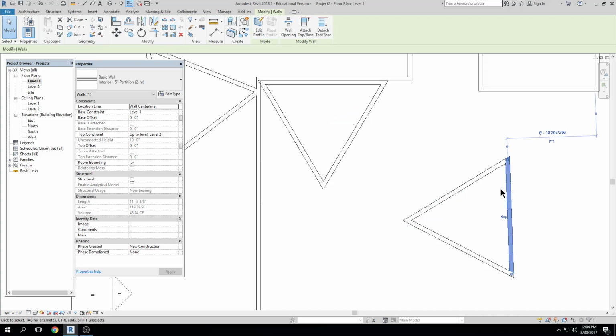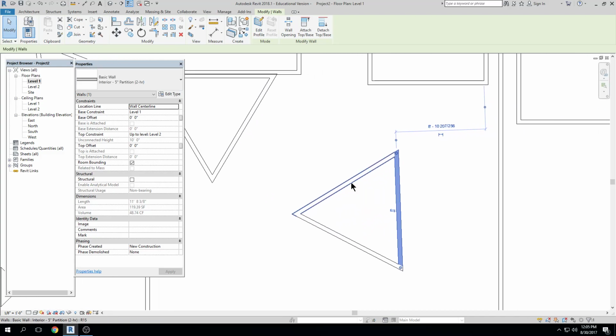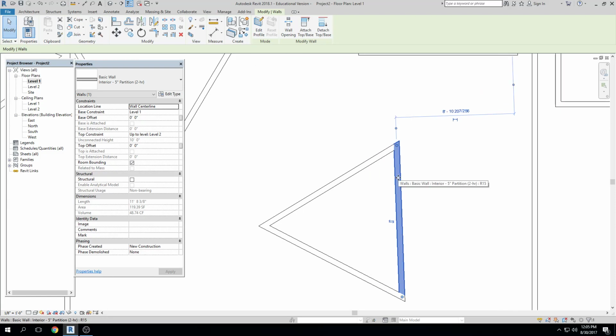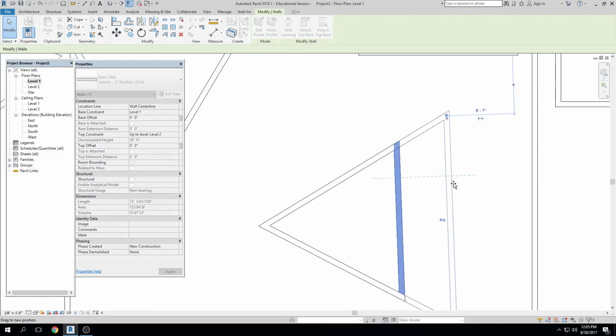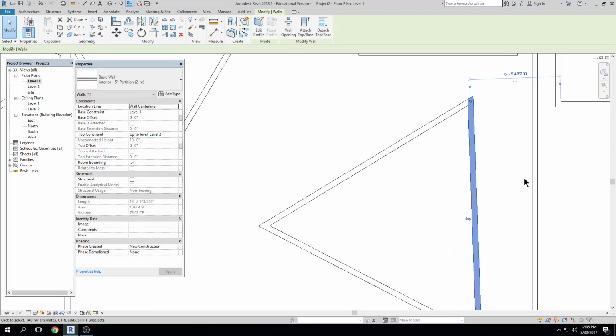Okay. I can also drag an object. I don't suggest it because I think that sometimes when you drag, you may also select something else that you're unaware of, which happens all the time. Probably where most mistakes happen is when you're new at Revit and you think, oh, I'm going to make this bigger, I'm going to drag it, which if you hover over a selected item and that little crosshair pops up with the 4 arrows, if you click your left mouse button and hold, I'm dragging it out, let go, right?